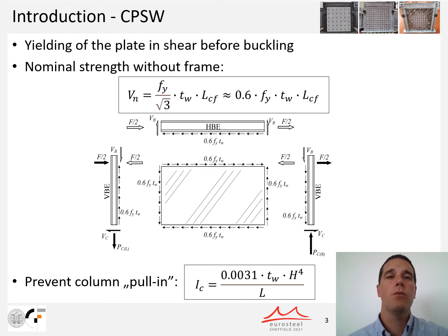In steel plate shear walls, transverse forces are exerted onto boundary elements, which therefore need to have adequate strength and flexural stiffness. These requirements are usually easily satisfied for intermediate beams, where the stresses from the lower and upper plate mostly balance each other out. However, this is not the case for bottom and top beams, as well as for columns, which are exposed to tension field actions only from one side.